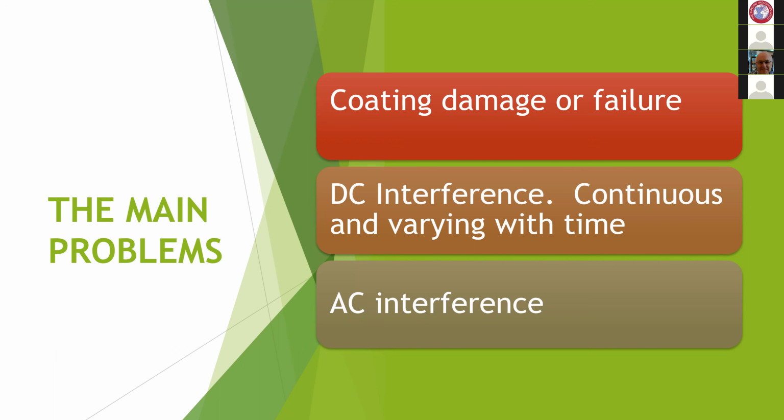And of course, some coatings are better than others. And there are sometimes significant problems that can be caused at the coating application plant. For instance, if they're in a bit of a rush and they speed up the process and they quench the pipe before any chemical reactions associated with the coating are complete, then you can get coatings that seriously underperform.